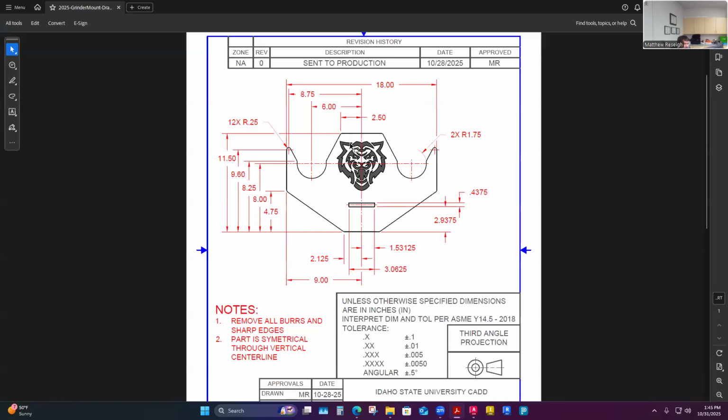From there, sometimes I take my boundary and put center lines on it. You can tell here, along the horizontal line, like our x-axis, and this vertical center line, maybe like a y-axis, that a lot of dimensions are taken from the y-axis. That's a pretty standard drafting and engineering notation: in some cases we'll pull dimensions from center lines. It's like we're establishing datums when we're dimensioning drawings.